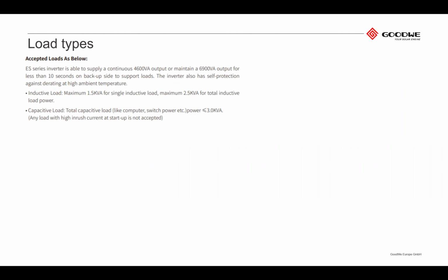Should we have our full 100 amp discharge available? But should that power factor of that device be poor, and that is drawing 6 times or 8 times or 12 times its rating, it will not work on the backup output of that inverter.